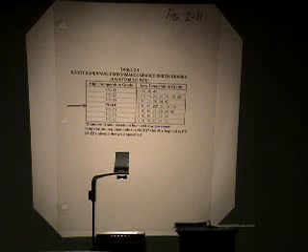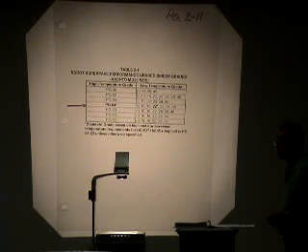But some of your major interstates, such as I-85 around Charlotte, and then here in Greensboro, Winston-Salem, we would require probably a 76-22 due to the number of trucks that do use that facility. Any questions on that?